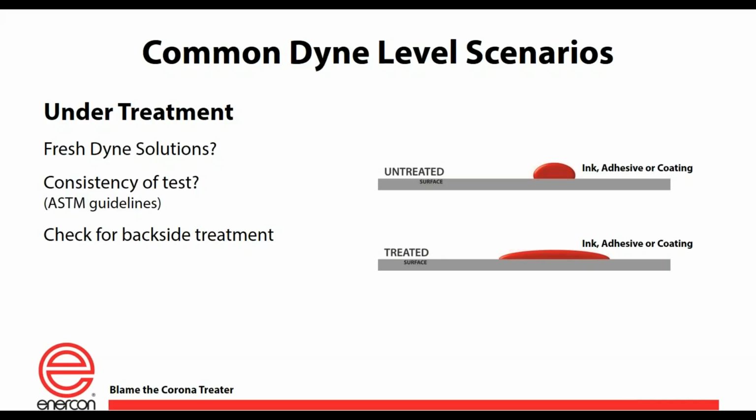And as that happens, that Dyne solution now is not accurate. It's not valuable anymore, really. So if you are a little lax relative to storing and handling the Dyne solutions, you may want to change them more often than 6 months. But generally speaking, 6 months tends to be the deal there, and you want to kind of keep that in mind going forward.